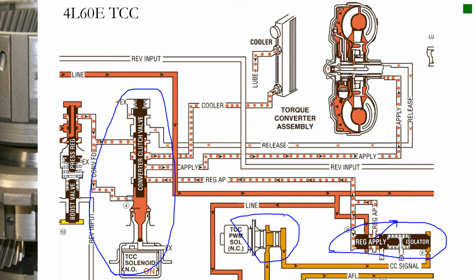But when you're in lockup mode, it looks at engine speed and output shaft speed, and it can calculate what the torque converter clutch slippage is. Assuming that none of the clutches are slipping in the transmission, they can use the gear ratio of whatever gear they're in, plus look at engine speed and output shaft speed, and figure out how much the torque converter clutch is slipping.